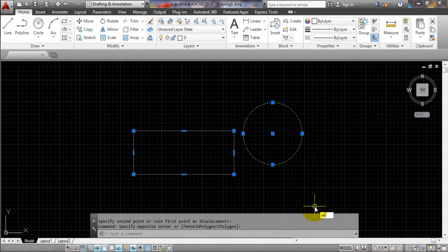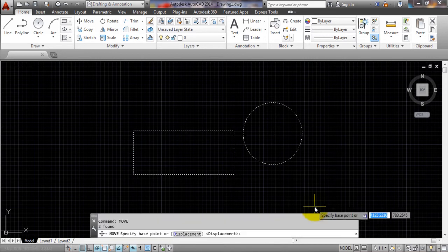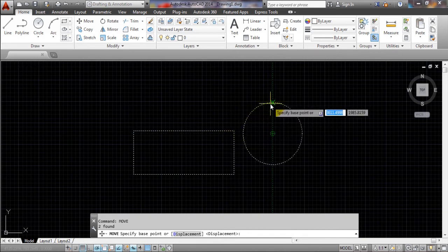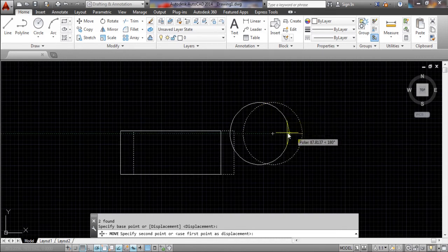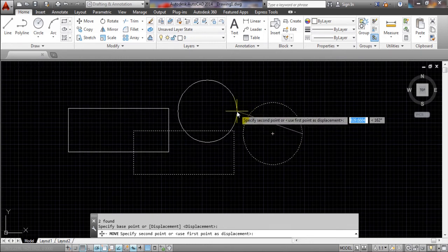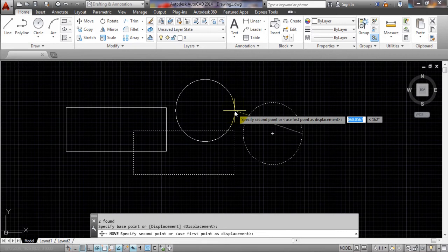And also I will show you again, and I want to move all this together. So right move command, and here it says choose your base point, and also you can choose whichever you want. The point is not important now. You should decide it according to your drawing.